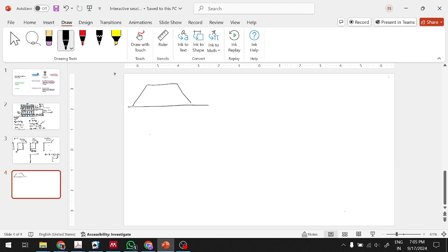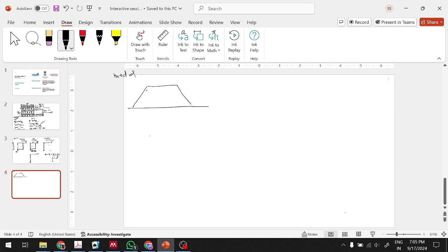I am modeling this embankment in a finite element method software, in which I have divided the embankment into a number of small regions. Now, for each region, I will calculate the effective stresses and the loads. So this region will not specifically be only sigma 3 and sigma 1, isn't it?